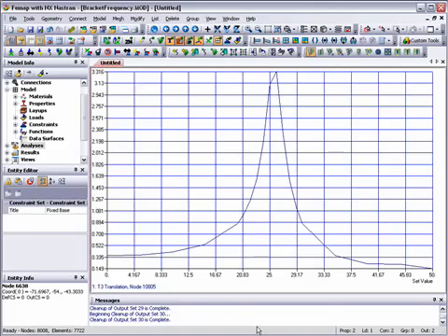Therefore, with the requirement to maintain a deflection of less than 1 millimeter at the motor center of gravity node, any dynamic base excitation loading with a frequency between 20 Hz and 30 Hz would require a redesign of the bracket. This shows that in many cases, a simple static analysis review is not enough. Femap with NX-Nastran can take the analysis further and model a more realistic representation of the design and its working environment to give more accurate and complete answers.